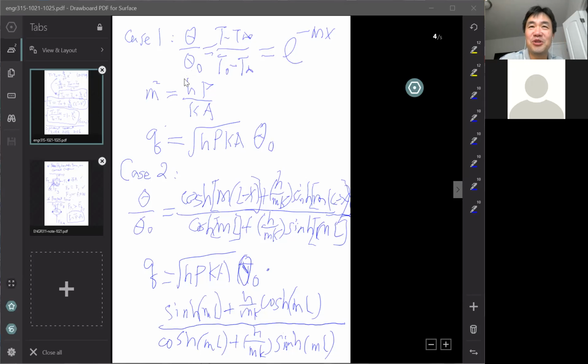It's not the heat source problem. Yes, it is the base temperature, at the base. T0 is the temperature we know, right? It's what the temperature on the wall should be without the fin. So theta 0 is the base temperature minus T infinity. This is basically a simplified version of the temperature equation. We use theta to make it look simpler, because the equation is long and we always want a shorter equation. It's simpler to write on paper.